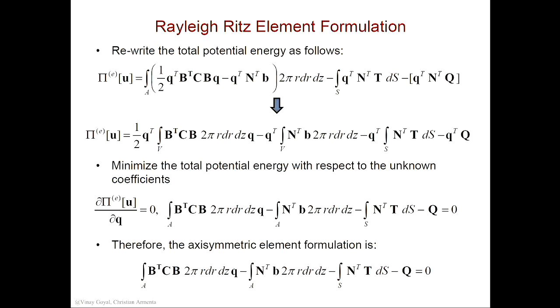And this is pi, by the way. I basically made that B bold. Okay. So just to simplify a little bit more for our purposes. And then I can now minimize this equation, which is pi, relative to the Q's. Each of the Q's, Q1, Q2, Q3. How many equations will I get? I'll get 2m equations, because I have m nodes and 2 degrees of freedom per node. So I should get 2m equations when I do that.